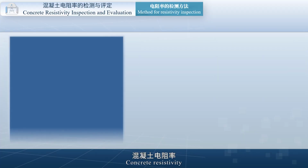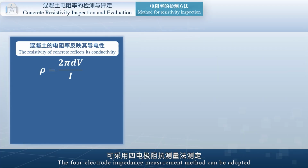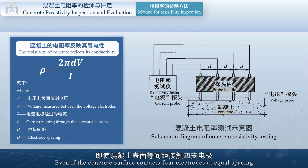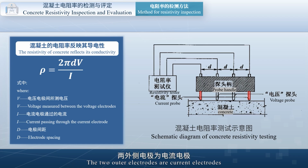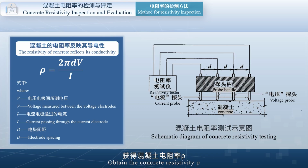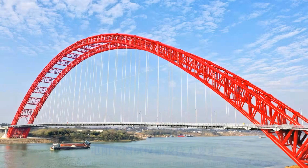For concrete resistivity, the 4-electrode impedance measurement method can be adopted, in which the concrete surface contacts 4 electrodes at equal spacing. The 2 outer electrodes are current electrodes. The 2 inner electrodes are voltage electrodes. By detecting the concrete impedance between the 2 voltage electrodes, we obtain the concrete resistivity ρ.